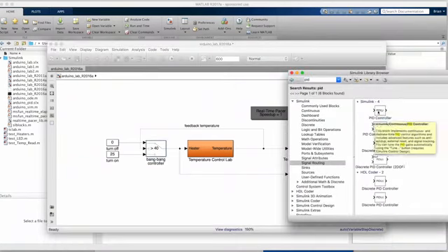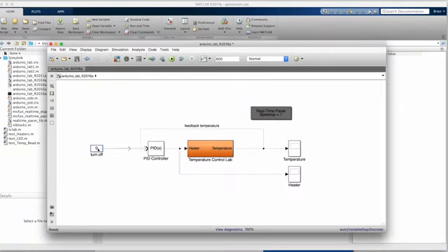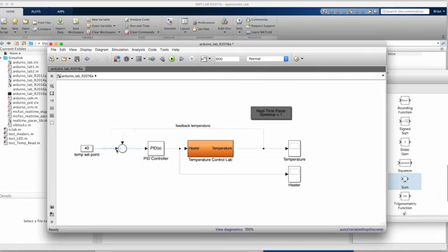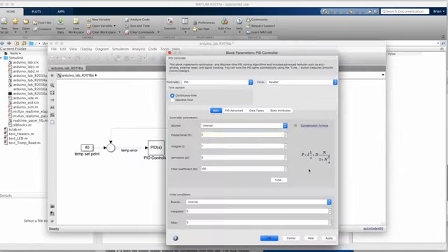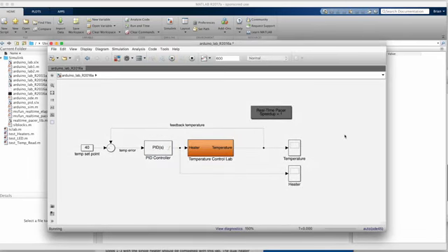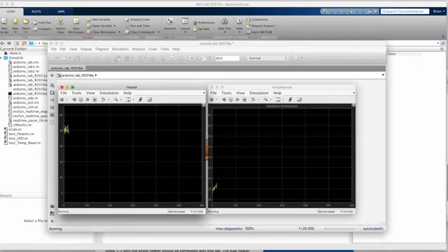We need a controller that can set the heater high at first to heat up quickly, but back off earlier to slow the rising temperature before we overshoot, and we can do that with a PID controller. I'm using the built-in PID controller with Simulink, and I set the P, I, and D parameters to a first guess. And if I run this, you'll notice a few differences from the Bang Bang controller.